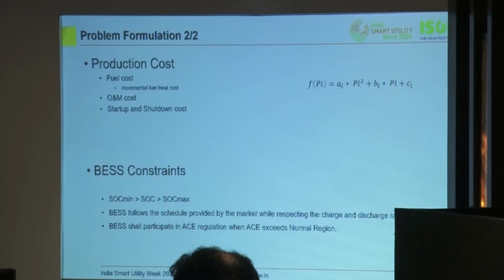Among them was the SOC. So that is first and foremost. The minimum SOC we keep is 20%, which is configurable, and the maximum we are going up to is 80%. And then apart from that, we had to ensure that this battery system should aid in case of any emergency. Whenever there is a requirement, it should be able to aid in maintaining the stability of the system.